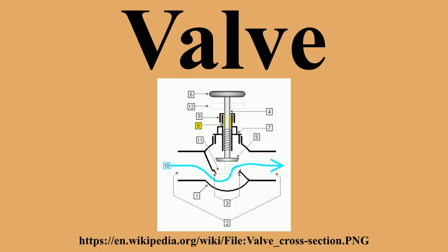Valve balls. A valve ball is also used for severe duty, high pressure, high tolerance applications. They are typically made of stainless steel, titanium, stellite, hastelloy, brass, or nickel. They can also be made of different types of plastic, such as ABS, PVC, PP or PVDF.